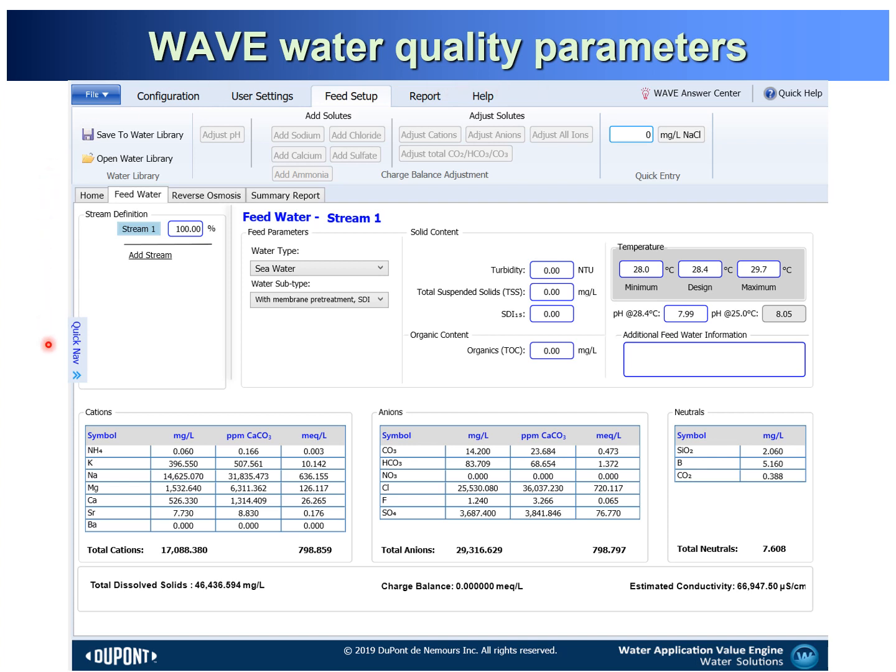First you collect your water, and then put in all the different known concentrations such as ammonia, potassium, sodium, barium, or some CO2, bicarbonate, carbonate, and then sulfate, with different temperature, pH, turbidity, total suspended solids, SDI, and the concentration of organic compounds.